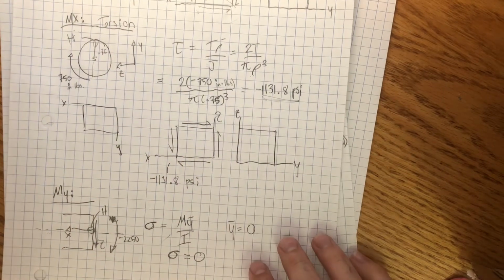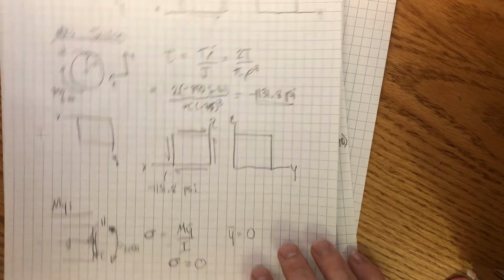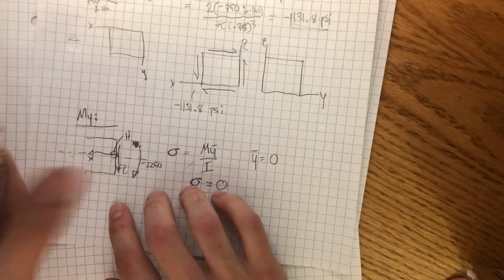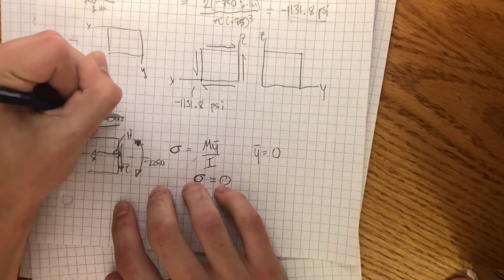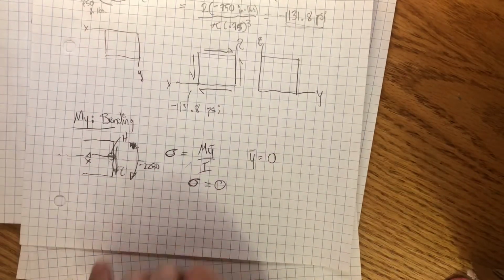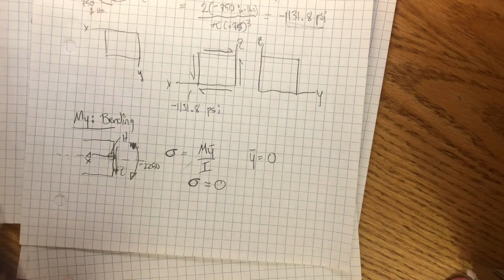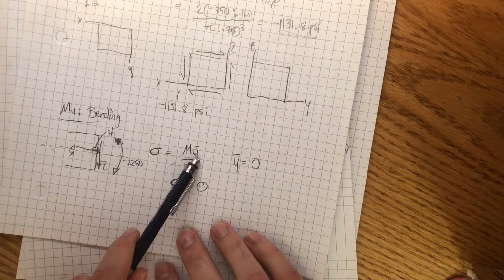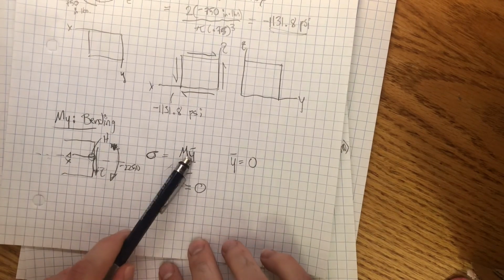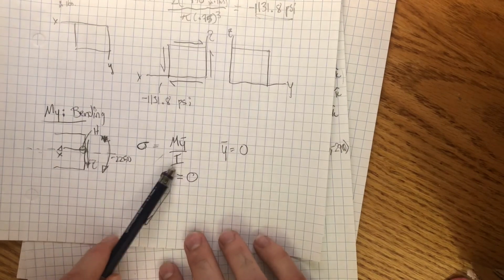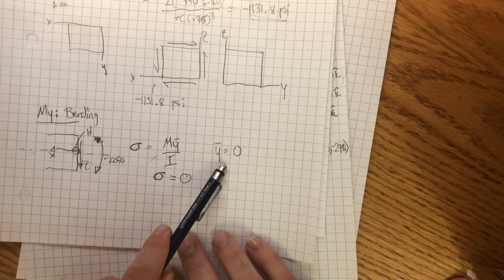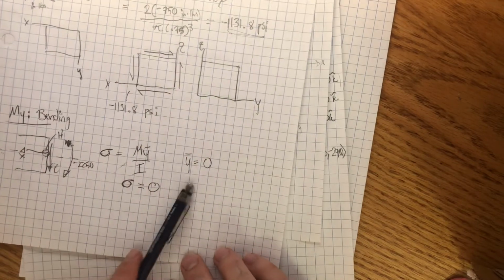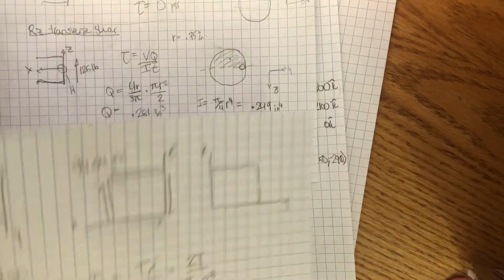That is because we got a negative value. Now, the moment about y, this we knew to be bending, because it is not going to twist, it is going to bend. But what we also knew is that you need the formula moment times the distance from the point of interest to the neutral axis over area moment of inertia. And because the point of interest was on the neutral axis, we knew that distance was 0, so we got 0.